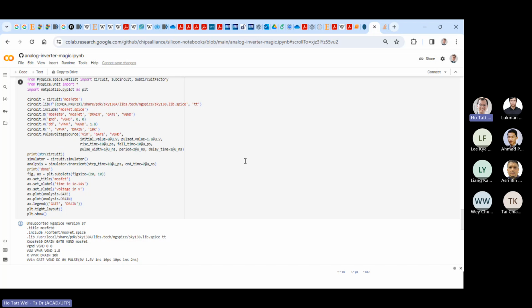In the case of the analog inverter alone, you are probably only driving the junction capacitor, the 2P or 3P parasitic, whereas for the fan-out of 4, you are driving 4 times the input gate capacitance plus that parasitic capacitance. So if you really want to normalize it, the analog one must actually be driving 4 inverters. Then it should be the same. That's the first thing to check.